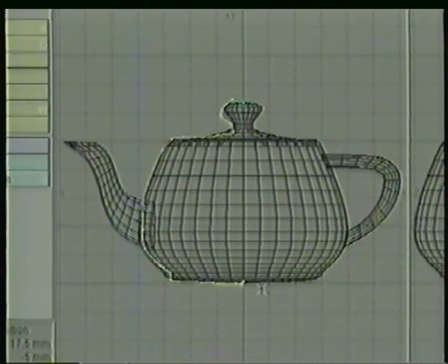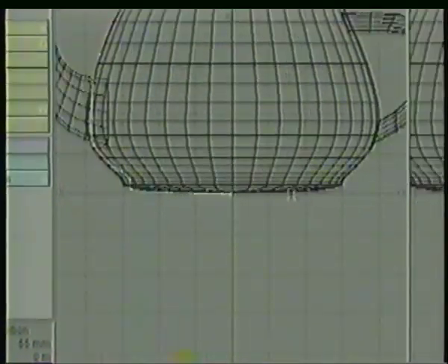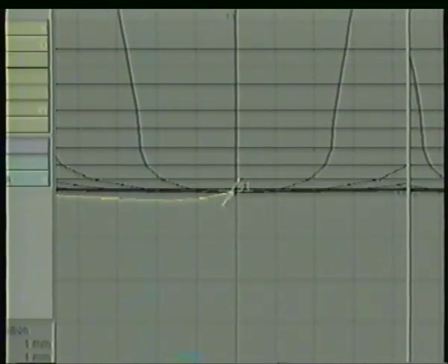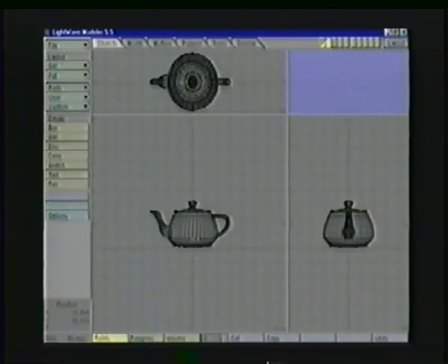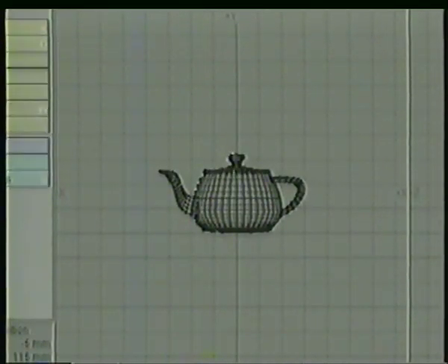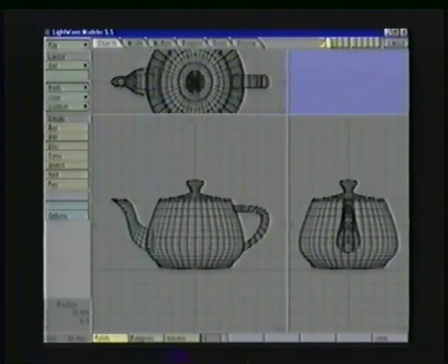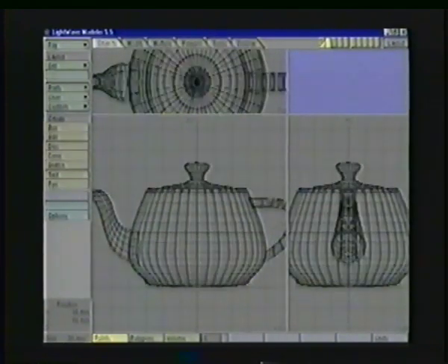It's not undoable. It's a simple matter of once you've made that curve with the sketch tool, you're going to find if we zoom into the bottom here of the teapot, you'll notice there's a lot of little points that didn't do quite the right thing. I'm going to do a lot of cleanup, probably using the drag tool or selecting points and deleting them. And I may end up spending more time making this into a clean curve than is worth it. So I'm going to delete that curve. I'll zoom back in with the period key a little bit.